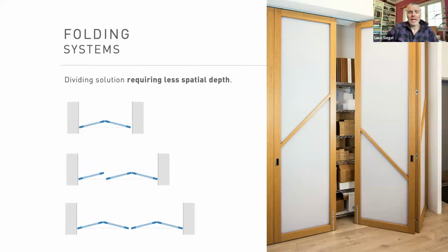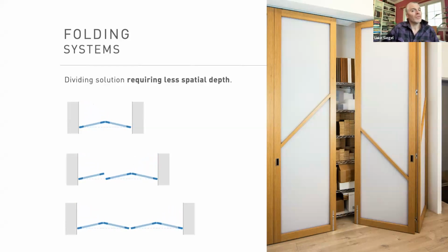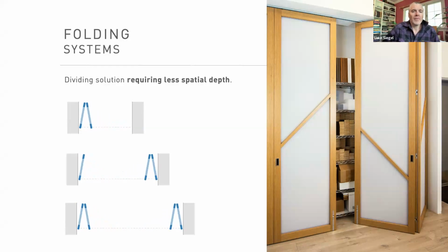When the panels slide, you can see how they cantilever and hang themselves over there. It puts a lot of stress on the hinges, on the pivot points, on the lead carrier. So narrower is better. There are systems out there that you could work with that are okay for wider, but with no floor track, if you want to keep it beautiful and make it easy to operate, 3 foot wide max is how we do it.